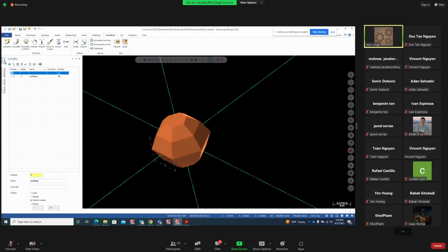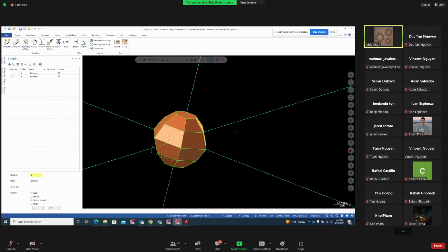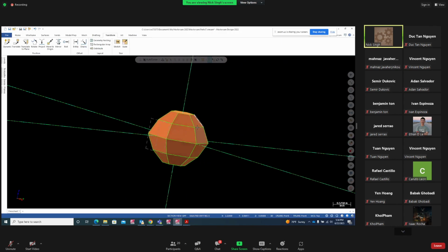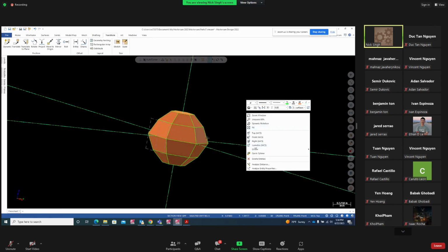So go to level. You can turn that on and off. And here level 1, you can name it, it's my geometry. Level 1 is my geometry. Hit enter. Level 2 are surfaces, level 1 is your geometry. So that finishes project number 5.